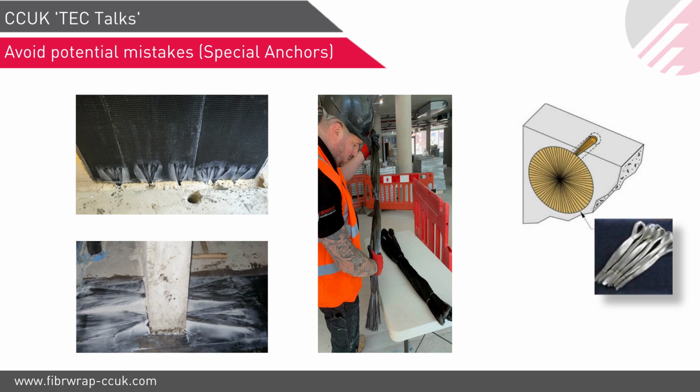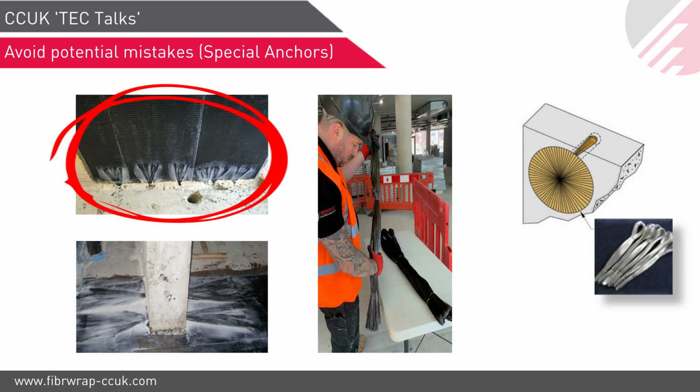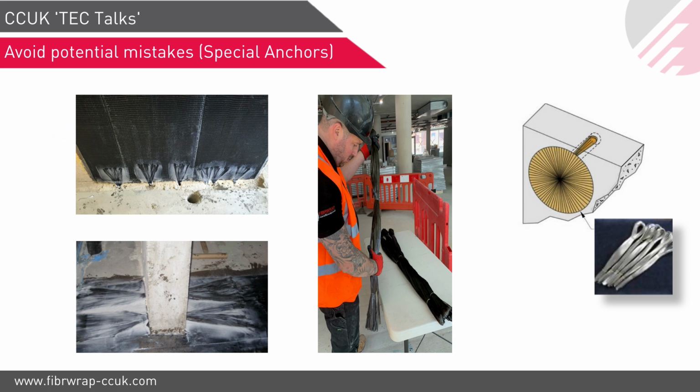And similarly, the image on the left hand side, the top image, is showing strengthening of a shear core, in which we strengthen the vertical element but use these anchors to transfer strengthening between the floors. So the holes were drilled through the slab to connect the strengthening on the floor above to the floor below.